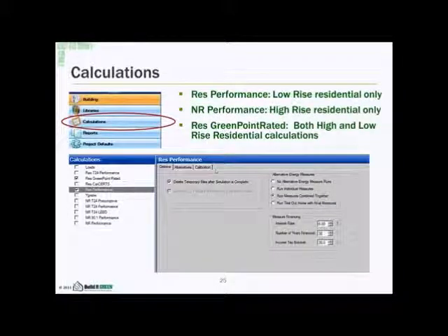So going back, when you click on calculations, you can see a bunch of different tabs. On the Options tab, we're going to click this radio button, Run Measures Combined Together. If you want, you can go into more detail, but it won't make any difference for your savings calculations or your compliance calculations. It's just more for reporting for your clients. If you're doing any type of finance calculations, you can put that in. But we're just making sure Run Measures Combined Together is selected.